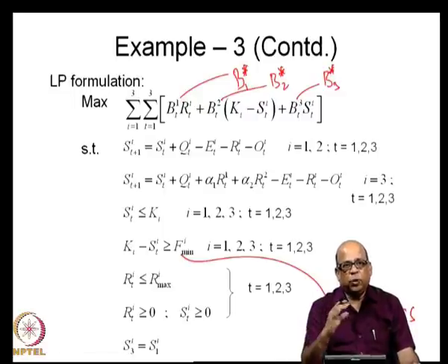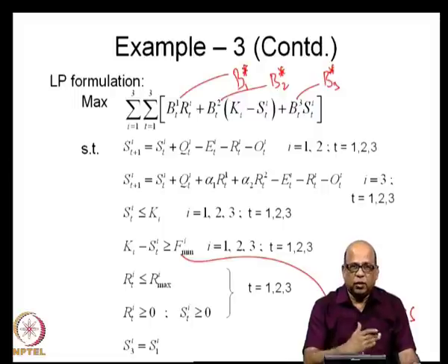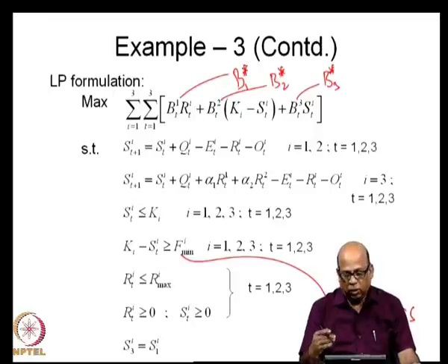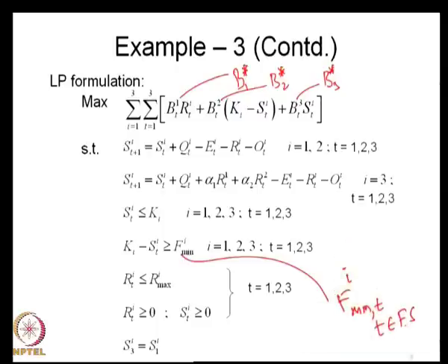Let us say in July you may specify something at Bargi reservoir, and then at Narmada Sagar reservoir you may specify some other freeboard in July, but in August these two values can be different and so on. So, in general you can include this as F min t, which varies from time period to time period at the reservoir I for t belonging to flood season, and for t not belonging to flood season, this can be just 0.